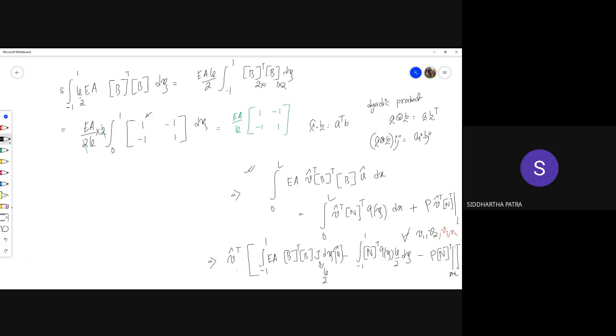And this one we would call the element stiffness matrix of the bar element. Okay. And if you have not noticed it carefully, the stiffness matrix for a spring essentially looks like this: K, minus K, minus K, K. We had done this a few classes before, which essentially means K in this case is equivalent to EA divided by LE.